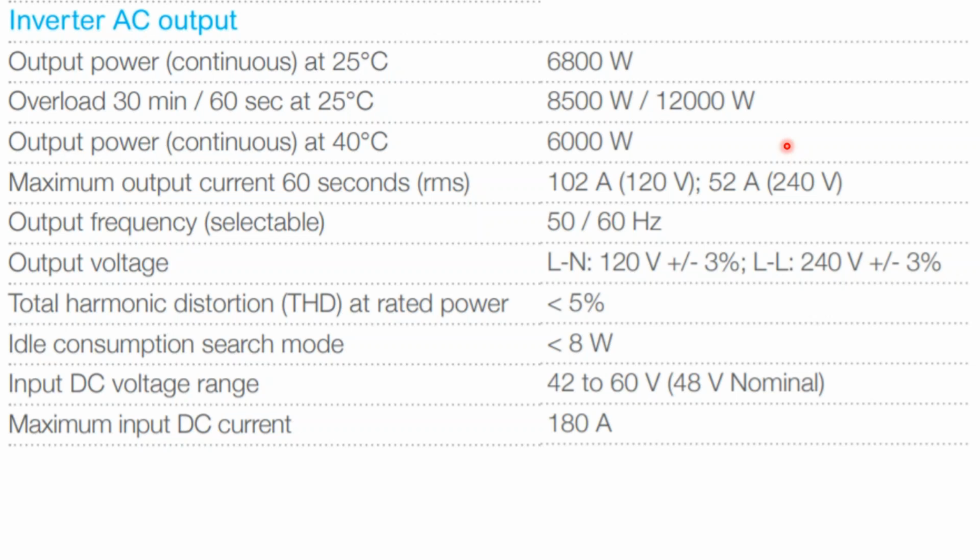Most electric service panels are 200 amp panels. And so if I have a 50 amp output, really two of these inverters would only get me up to 100 amps. And that's where a generator can come in and say, okay, well normally on a home, you're not pulling 200 amps. You're pulling much less than that. But on a solar array like this, we're only getting up to 100 amps.